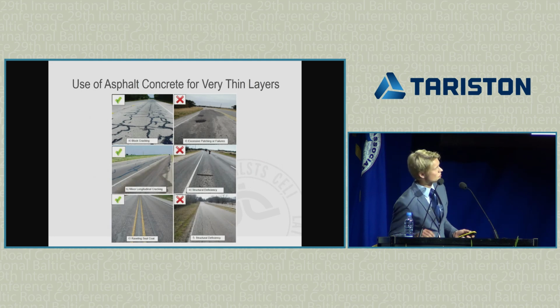So in this picture, there are recommendations. For example, if you have block cracking, then you have to treat cracks, fill them with mastic, and then you can use thin overlay. But on the other hand, if you have, of course, structural deficiency, then it's not recommended to use thin overlay.